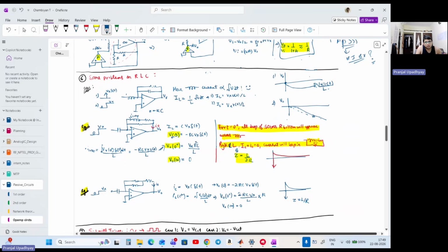So the current is now a unit step, and since this is a unit step current, what we can find is the value at 0 plus time, which is just simply this term multiplied by r, and there will be an additional minus sign because this terminal is 0. And so what we get is a positive value, which is Vx r square C by L, right? Simple. And at infinite time, we already can understand that this current that we established is just for t equals to 0 plus time.